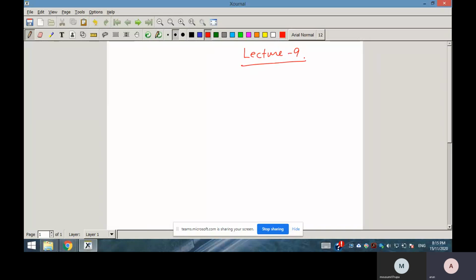So this zero location closer to the imaginary axis also will cause high control effort or a large peak in control effort. So now we will see how to avoid those two things using a 2 degree of freedom control.